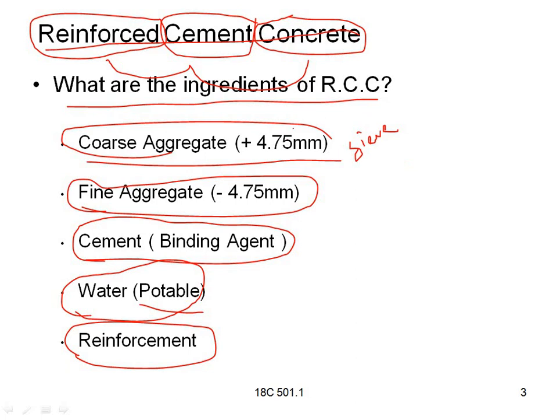So you can see this is a 4.75 mm sieve size, it will be round. This sieve is used in the laboratories. From this, some of the aggregates will be passing, but some will be retained on the sieve. This sieve is 4.75 mm size. Whatever materials are retained on top of the 4.75 mm sieve are called coarse aggregates.